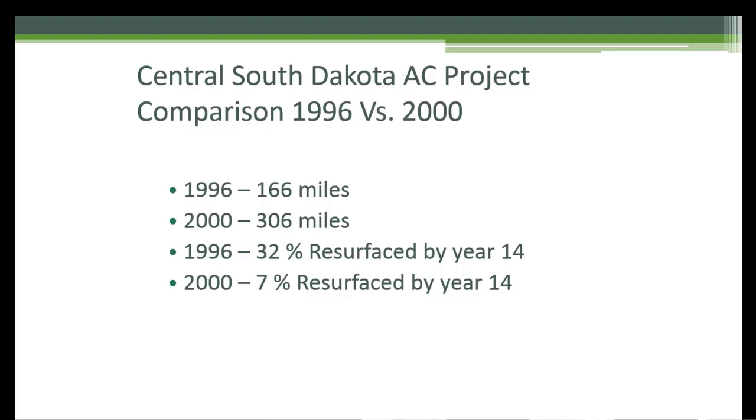And then post-2000, which again follows into the Superpave PG binder QC/QA era. And if you looked at that, there was a drastic thing that stood out. And I think this is the most under-touted data in both DOTs, in my experience: pre-2000, about 1/3 of those were resurfaced by year 14. So in other words, some type of overlay or mill and fill.